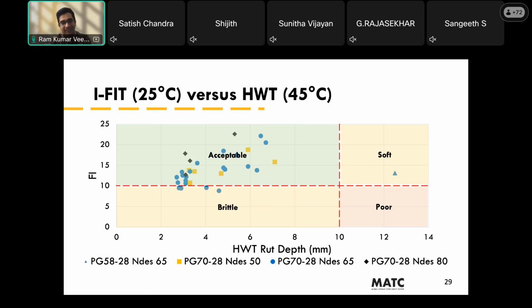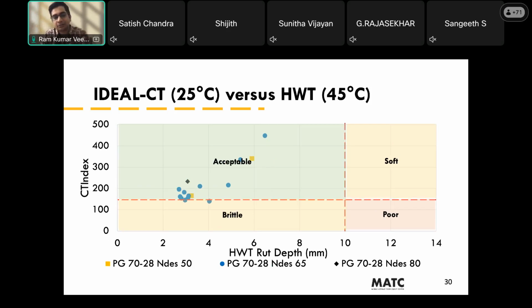However, when you're dealing with this balanced mix design, you need to think about this proposed criteria threshold. These are subject to change over a period of time as you evaluate the performance over a long period of time. And the proposed rutting threshold for these unmodified asphalt mixtures can change over the years. So they started off with 10 and they found good success with the proposed criteria.